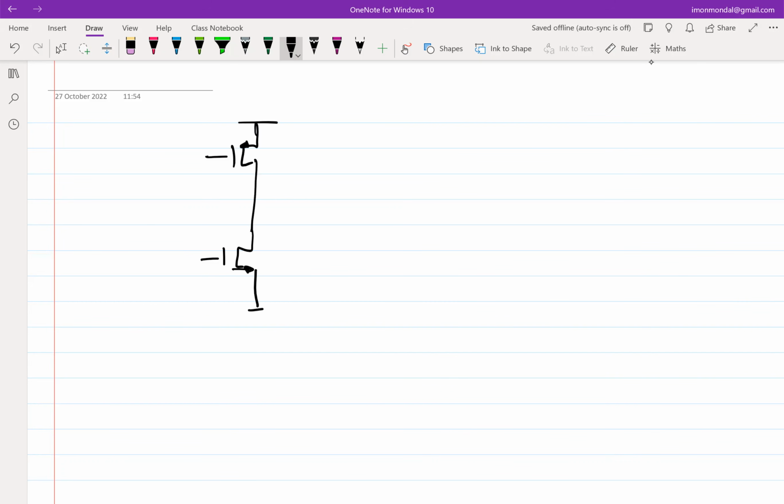And then we said that, if this is supposed to be behaving like a current source, I can as well mirror the current from somewhere else and feed it here. Then we argued that I can use the gm of that transistor also to increase the effective short circuit current, right? So we said that we will do this. And in order to give negative feedback, we have to connect in such a way that the negative feedback still holds. Otherwise, your inverter can go in. It has so many more points of operation. It can go either NMOS being off or linear or saturation or whatever.